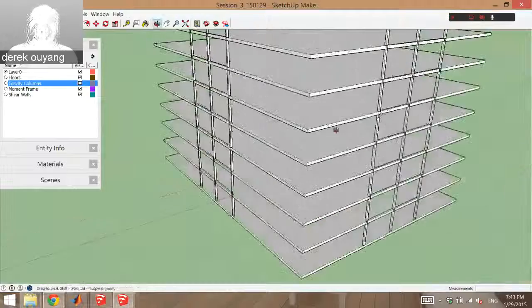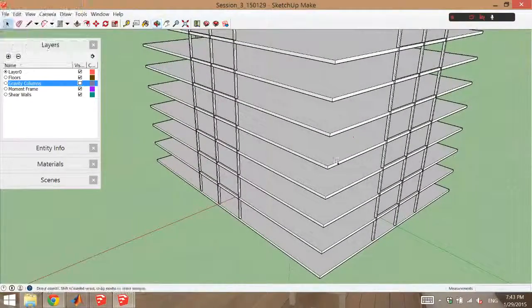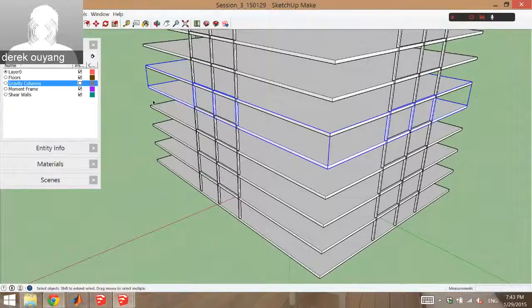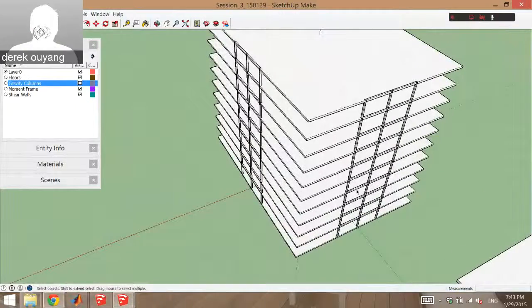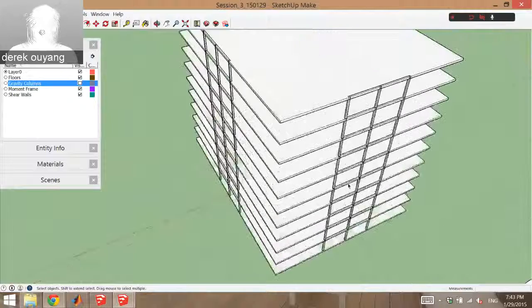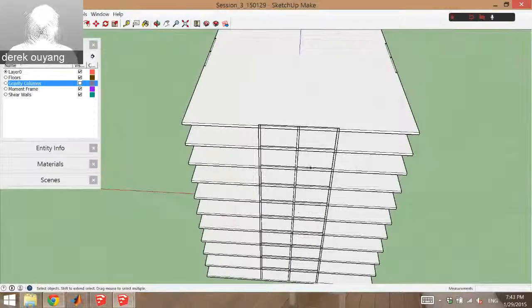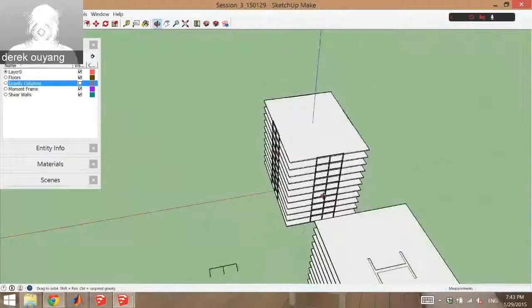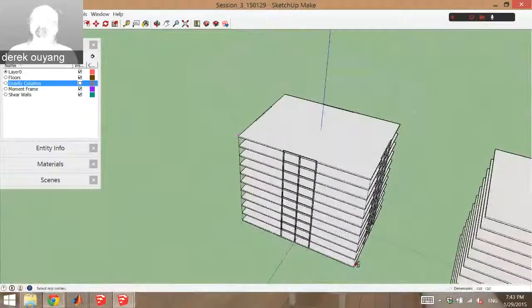First of all, which lateral system should we really be designing first in this case? Of these two options, this guy and this guy. We're going to design the most extreme one, right? Especially if we're talking about big members. It'll be in this direction of bending where this lateral system is going to take on the most, mainly because of the amount of wind that it's got to take up, right?